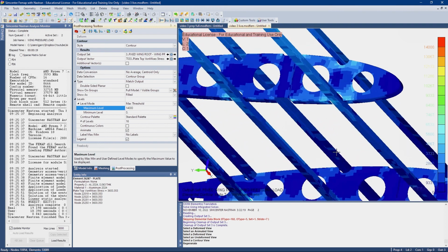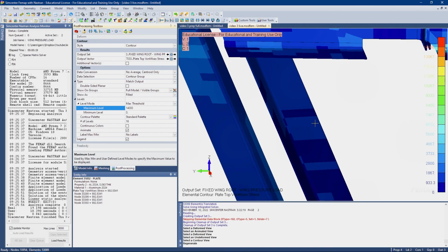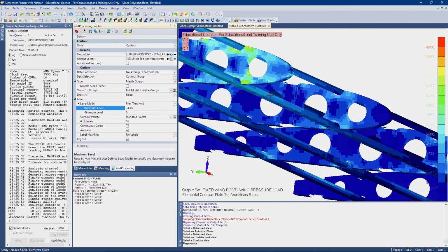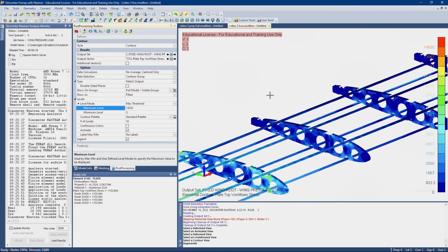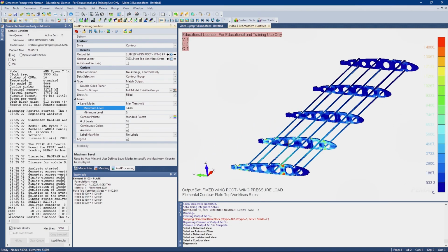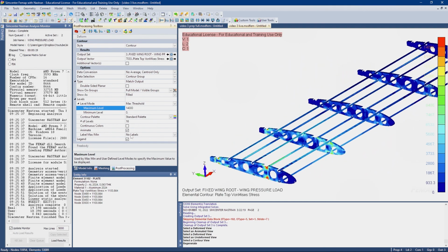Although, that being said, most of the stiffness comes from the bent flange here, not necessarily from the thickness of the material, because remember our discussion before about the ruler, like thinning out this material is going to be much less significant to the total stiffness of the stringer versus making the stringer taller. So you can play with a lot of parameters, and at the end of the day, you have a single finite element model for your entire wing. So you can change your geometry and arrive at something that works.